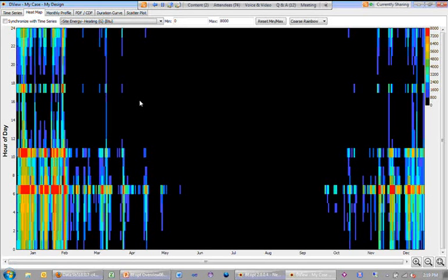And I guess we would recommend against doing two separate simulations, one for each zone, because our assumptions about appliances and occupants would mean that we're assuming each zone has its own refrigerator, oven, etc. Which you probably don't want. So we would probably recommend just modeling it as a single zone.